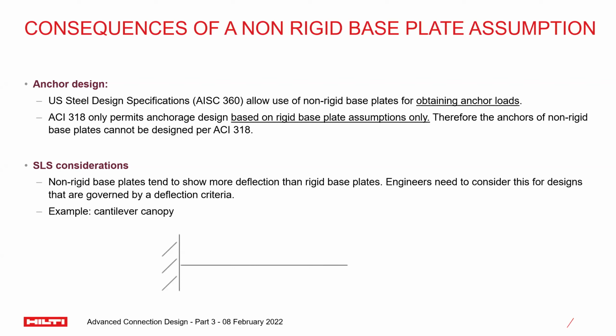And the second thing is again very obvious, I think, which is serviceability deflection. Anytime you have yielding, this basically is a sign of release of energy in a structure that can lead to some excessive deflection by default. So be aware of that and make sure that you have that on your mind before you even start the design.